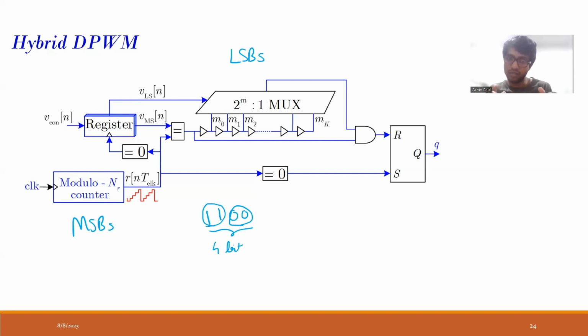We can either vary the output voltage of the DC power supply largely, like it could go from 0 to 3, 4, a large value. Or there's something known as fine resolution, where it can vary in small values like 0.1, 0.05, etc. Those are the fine ways we fine tune to get the exact value you want. And if we want to change it abruptly or rapidly, we have the coarse value. So that is how we are doing it.